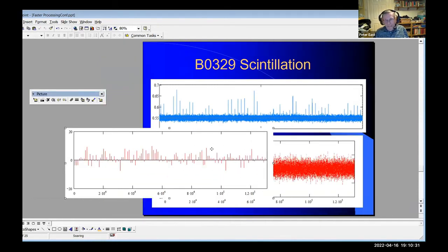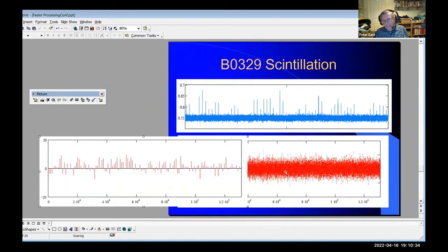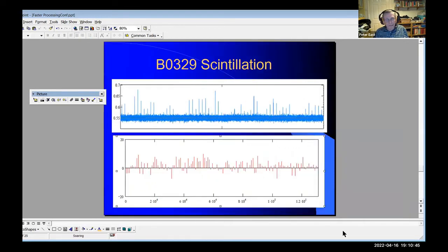Yeah, my equivalent data for the 128 sections by 1,024 points is just noise. You can't see any pulses there at all. But because it's digital and I know the bin number that the pulse is arriving in, I can select that bin number, and that's what I've done here. And what you can see is that there is evidence of scintillation just by looking at those bin numbers. There's some negative ones, but it's all largely positive, and that's another indication that you've got a signal that's integrating.